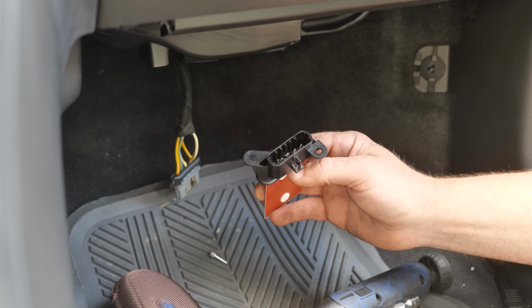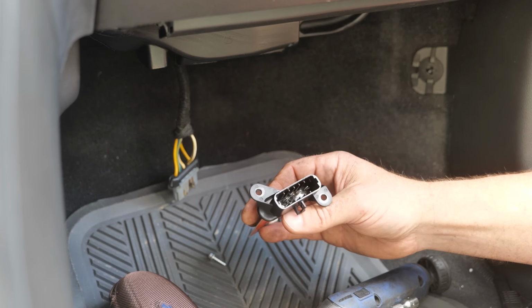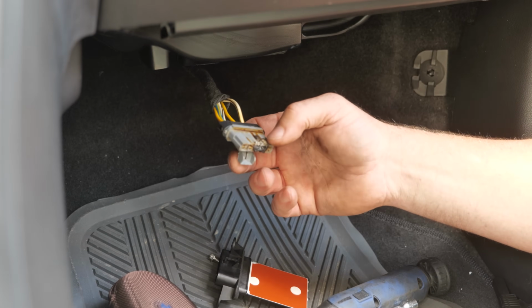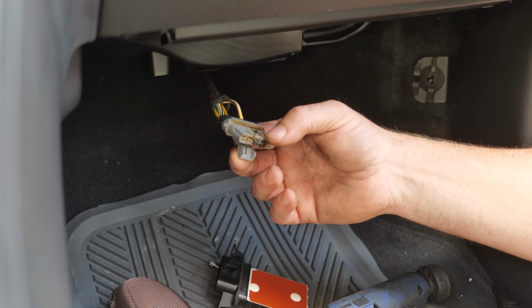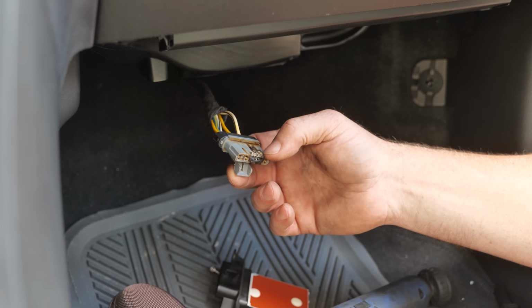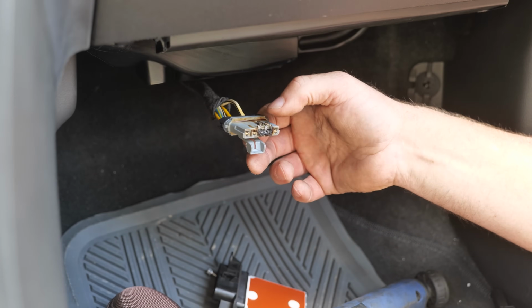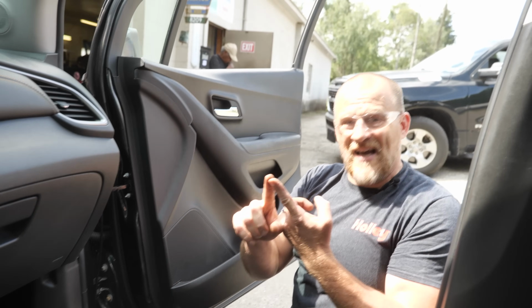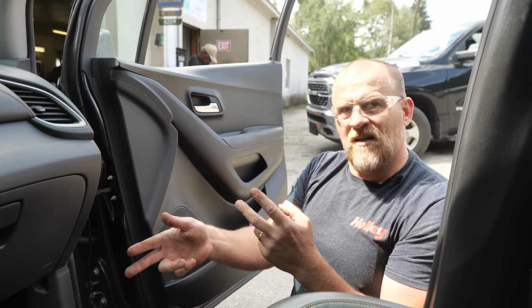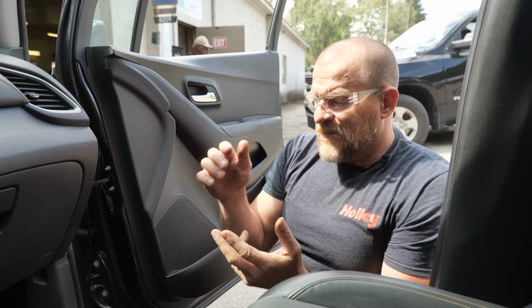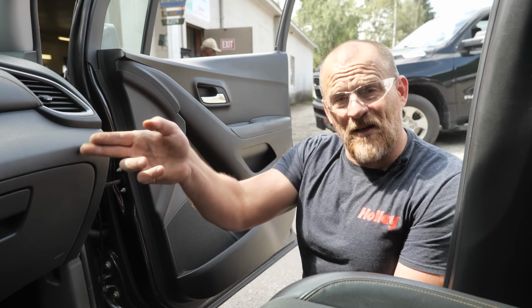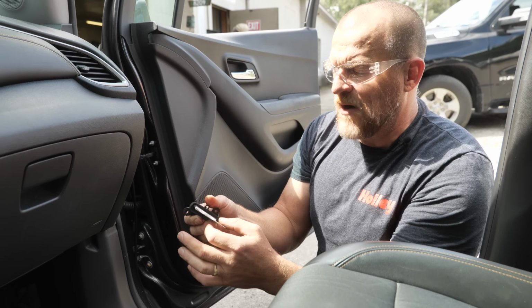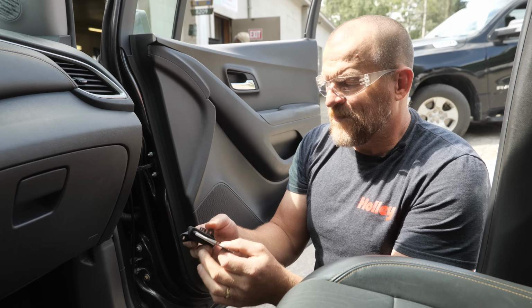I'll have to ask Pete if this was burnt at all on the last one. It could also be that it had issues before. I don't know this, but if it was burnt before and then making poor contact equals heat. So then what you have was a contact issue that caused this. So it's a couple things. A contact issue, poor terminal contact can cause that. Just loose terminals. Resistance equals heat. The second one would be, we addressed a plugged cabin air filter where this thing is not cooling properly. But in that case, I would think you would expect to see the burn in here, right? Not up in here.